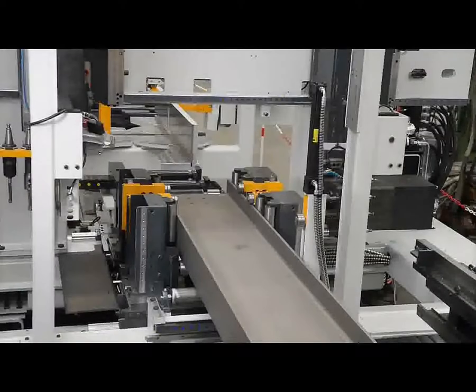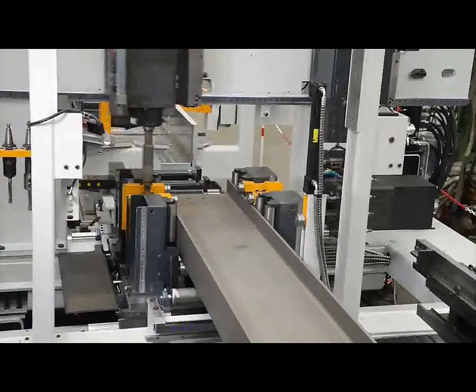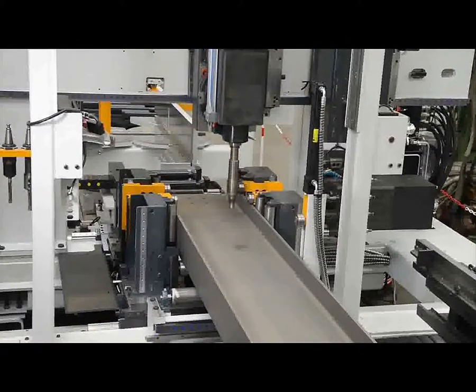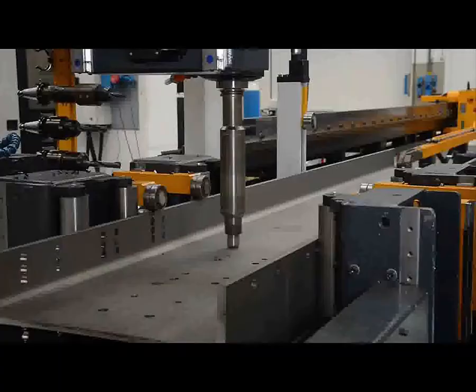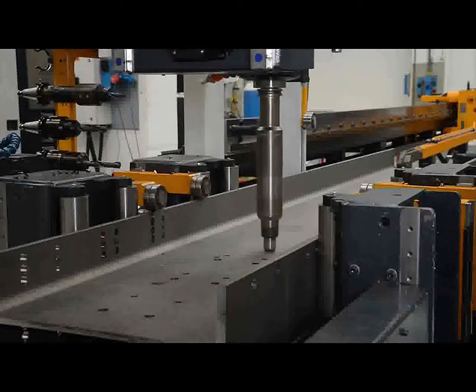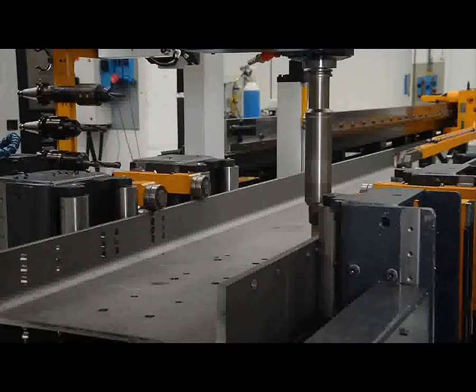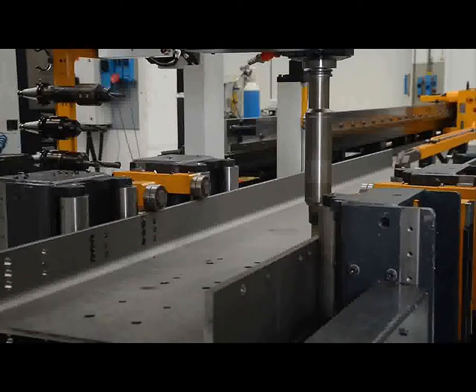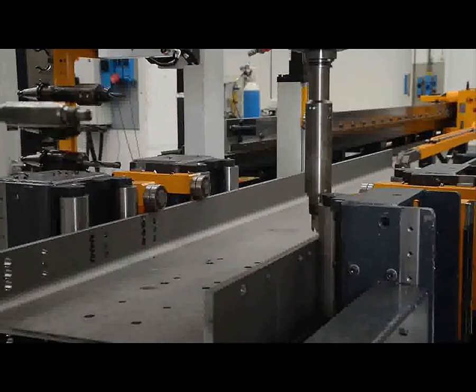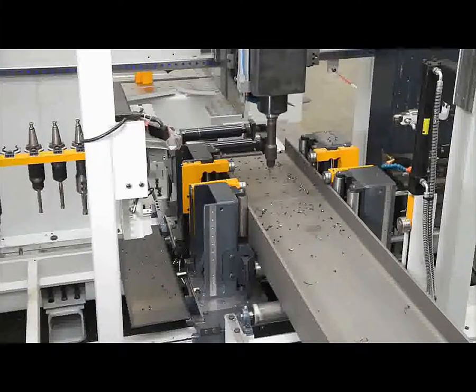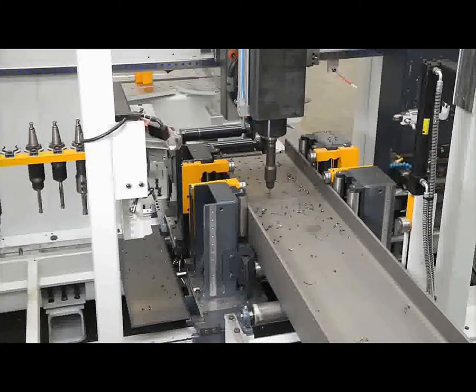Again, this one you can see it's already sawn the end there. What it's going to do is drill the holes, and it's going to do the layout marking first of all. So again, where the pieces fit up on that particular beam, it's going to do the layout marking so you can see exactly. The fitter just quite simply puts the plate against the line marking, no need to measure, it's all done directly from the Tekla model.